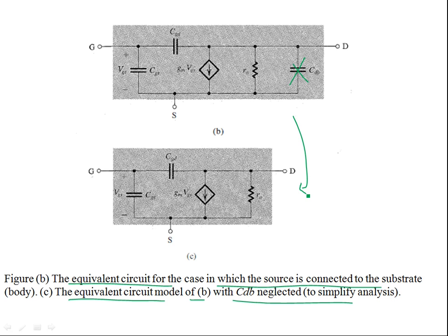analysis of the circuit. So this circuit can be analyzed easily by manual analysis, writing the KVL and KCL equations, and then you can write a transfer function relating the output voltage to the input voltage. So the transfer function of the form T(s), where s is the complex frequency variable, will relate the small signal output voltage V0 to the input voltage, which is over here in this case VGS. That's the input voltage. Output voltage is being taken from the drain.